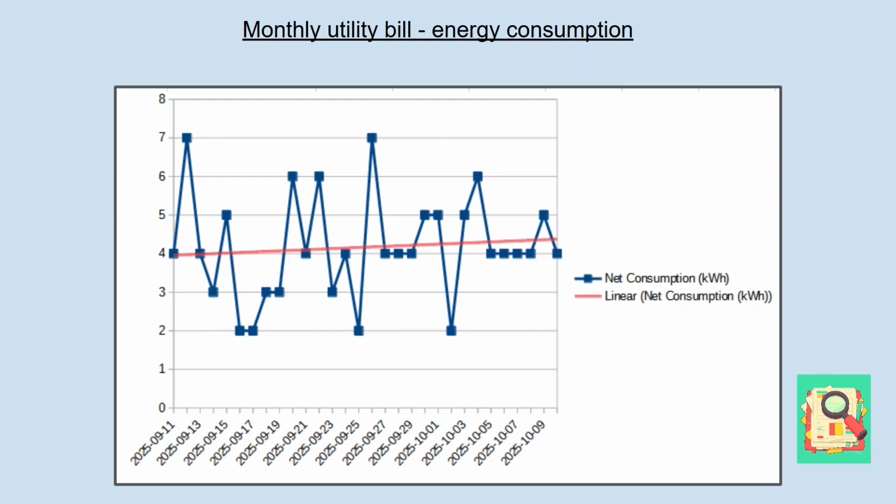So for example, looking at the day of September 27th, we see that the energy consumption is 7 kilowatt hours. But is that energy consumption within the first 4 hours of the day, the last 4 hours, or does it peak at noon at 7 kilowatt hours? If it peaks at noon and the energy is used within half an hour, we can see that the power requirement of the inverter is 14 kilowatt. 7 divided by 0.5. That is how you would size the inverter.